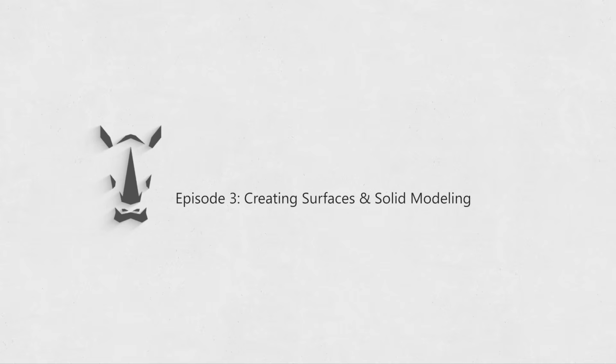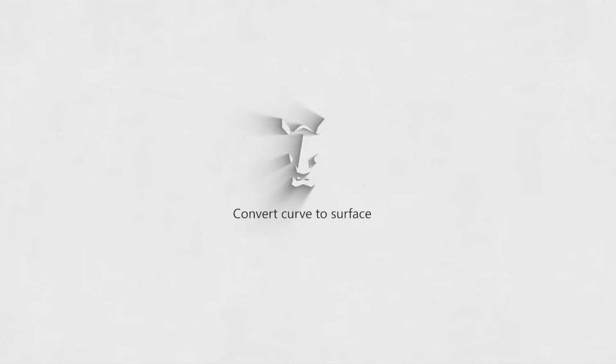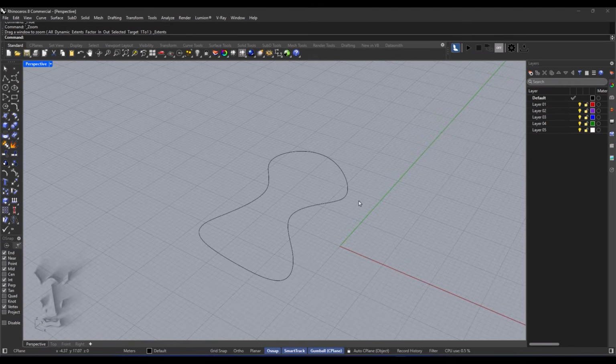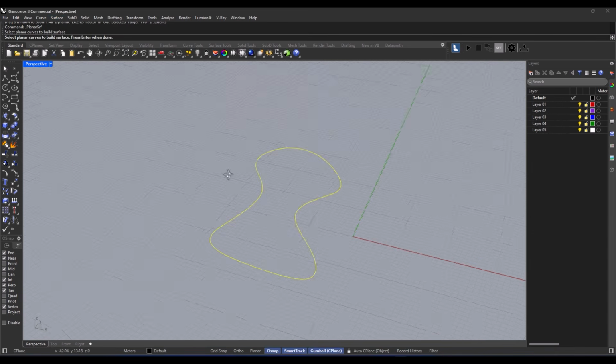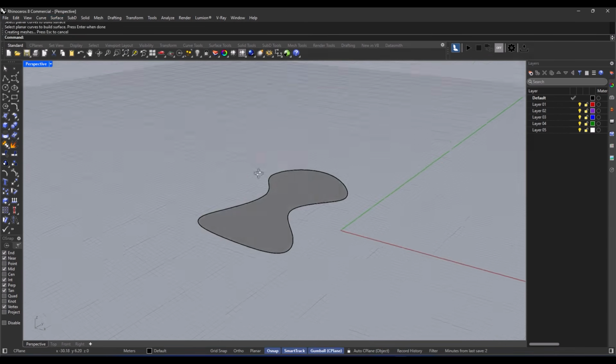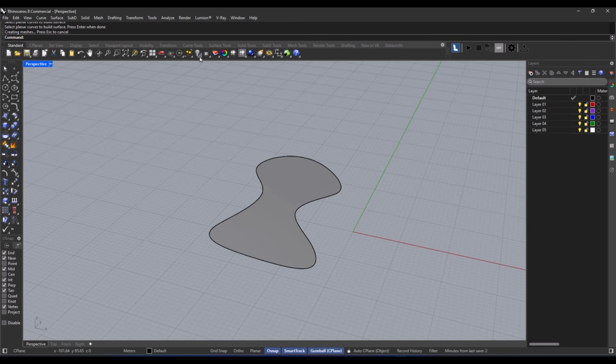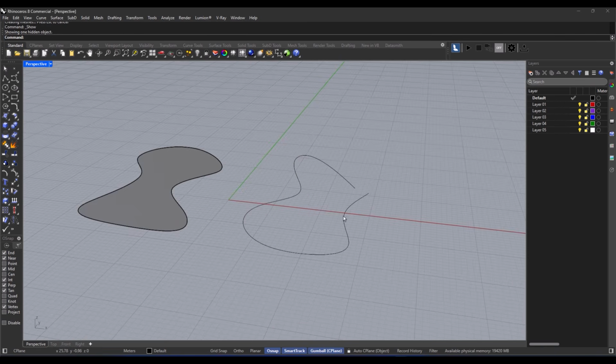All right, so we're talking about turning curves into surfaces here, right? So this command creates a planar surface from a bunch of planar curves that define the edges of the surface. But there are actually 2 main rules you really got to follow at the same time, or else you won't get that surface.